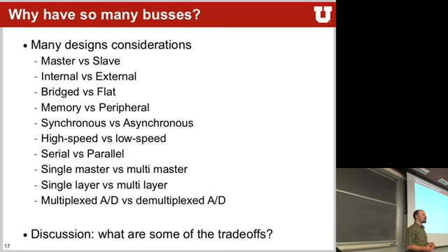Yeah. What else? What's a huge difference? Why would you have some buses, for example the AHB, why do you run the AHB only internally? A lot of wires. Right? Internally on a chip, you can have a lot of wires going back and forth between the different peripherals. You can have them 32-bit wide with 32-bit addresses, which would be 64 pins.